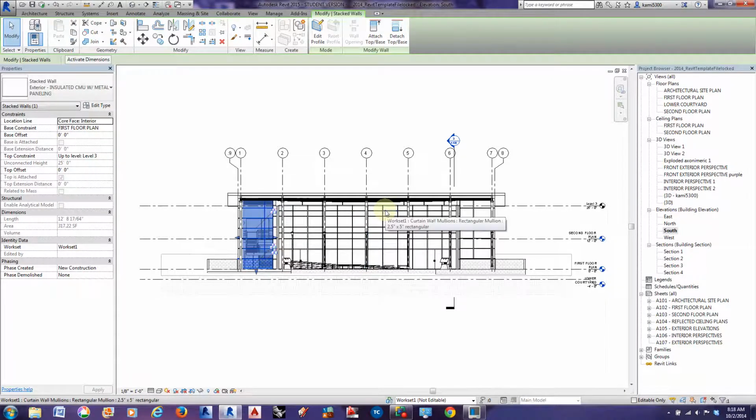I mean, we can, but if you went to cut it and set it in place, it's going to come up short on both sides because of the curve. So basically, we're still going to export it as a 2D surface, but then we're going to have to actually measure that length so that we can fix it in AutoCAD, which we may not get through all of today, but at least you understand that any curved surface, you'd have to do some legwork to get it to work.